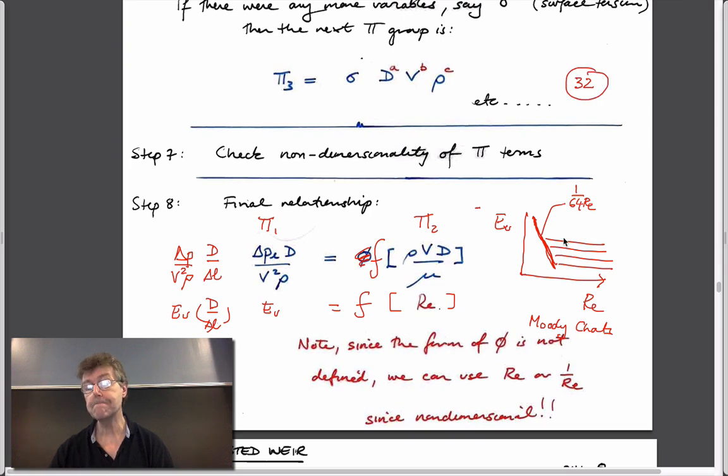And as we go at faster and faster velocities, all of a sudden the flow, instead of being this laminar flow, breaks down into this turbulent flow for different diameters of pipe. And so this relationship is something that we can surmise by doing some experiments with different diameter pipes or different fluids, but nonetheless, in the laminar regime, there's a single relationship that we get for every single pipe, every single fluid, with every single density and viscosity.